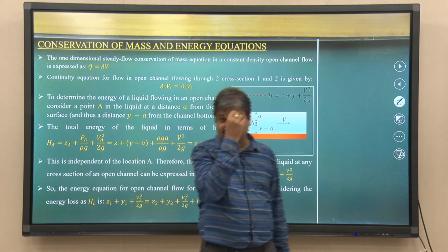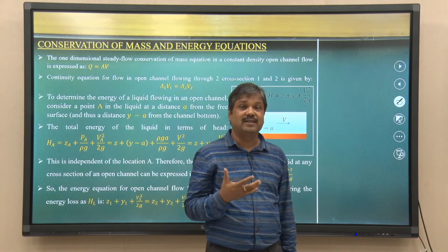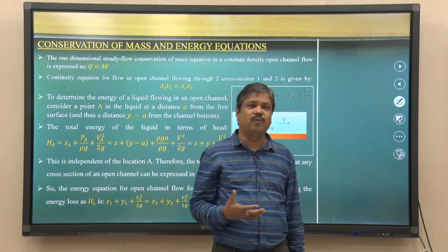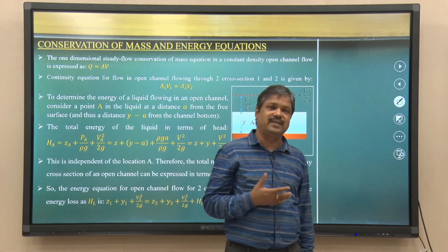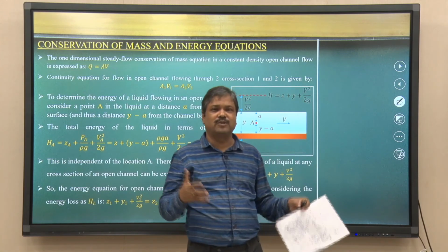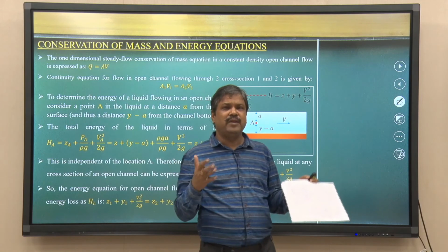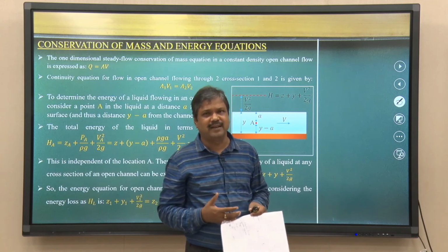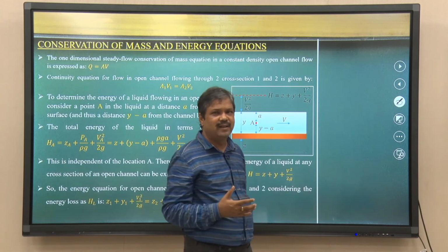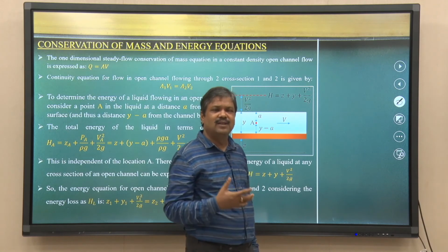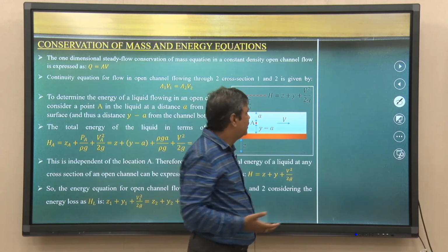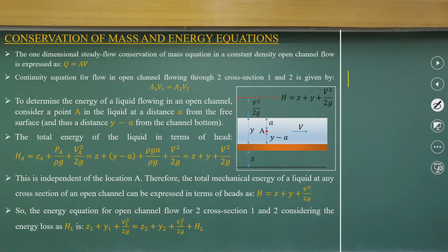Now, as I said, we follow the basic integral approach concept, the average conditions. We are not looking at the detailed flow field as we discussed for the differential analysis part. When you design open channel flow, we may neglect the velocity distributions, how it is happening, how these turbulent structures are created. If we know the average velocity, the energy losses and the flow depth, then we can use the one dimensional equations which we already derived,